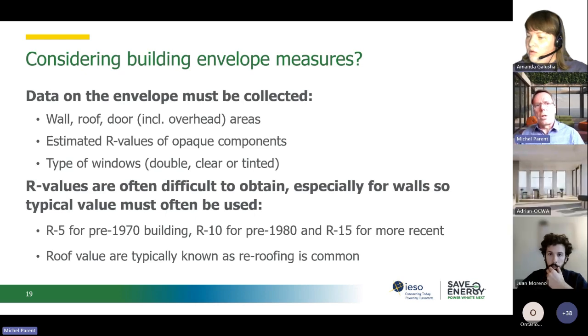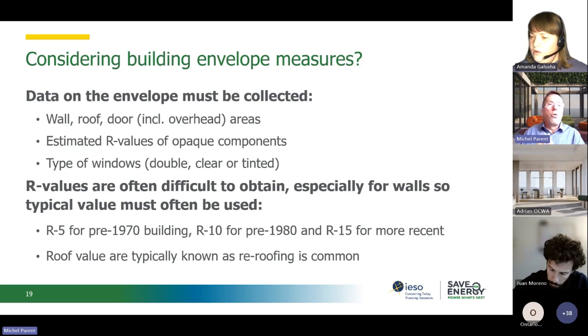Last item about collecting information. When you collect information, I've talked about HVAC systems, but the building envelope does impact your HVAC system, does impact how much heating and cooling is required, as well as it will impact, for example, your condensing boiler. If you've got a condensing boiler, what temperature you can return to, what temperature you can supply. So the quality of the building envelope. So you may need to collect information. I usually would not do that unless you plan to do something with your building envelope, or you want to have a whole energy model, let's say using RETScreen, of your building.